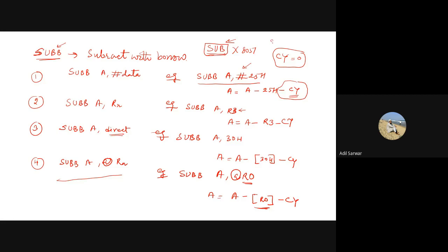So it is better to add the instruction CLR C to clear the content of the carry flag before you use the SUBB instruction, if you are working with two 8-bit numbers. But if you want to subtract two 16-bit numbers, then initially you have to make it 0. Then when you proceed with the subtraction, you can have the same type of operation as you have in ADDC.